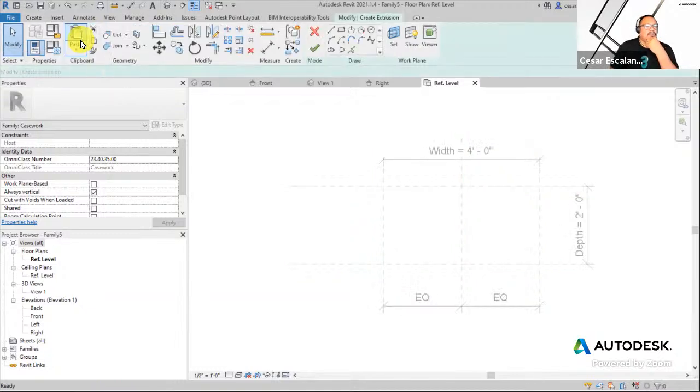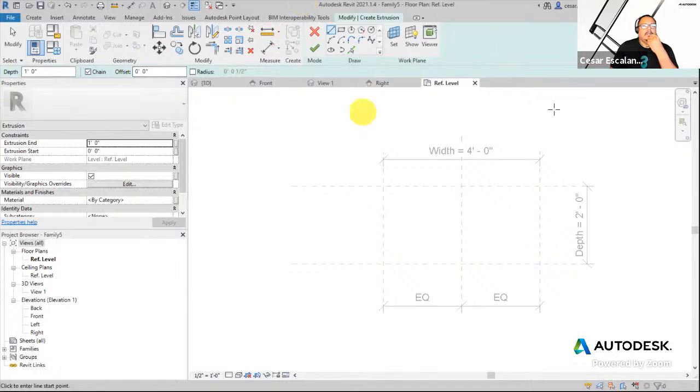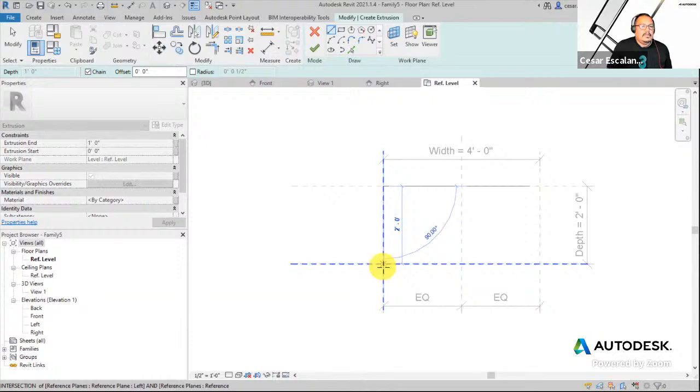And then you select the extrusion button, and then it's going to disclose this temporary tab, which has the draw tools that allow me to create sketch lines. So a sketch line is a purple line that defines the boundary of an object. And you can use all these tools and modifiers to draw the boundary of a solid. So all I'm going to do is snap to these intersections, and you can see how it automatically snaps to these intersections.